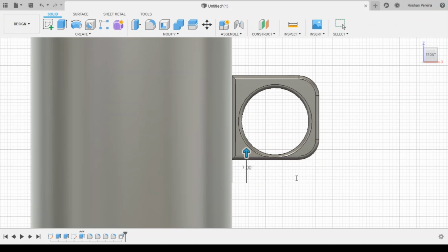Okay, so I have made it -7. Why -7, even though it's going on top? It's because the bottom edge is actually made to extrude in the down direction, so the top direction is the negative direction for it. Whereas if you extrude from the top corner, like how we did before here on top, the positive extrusion is on the top side, and negative extrusion was on this side.